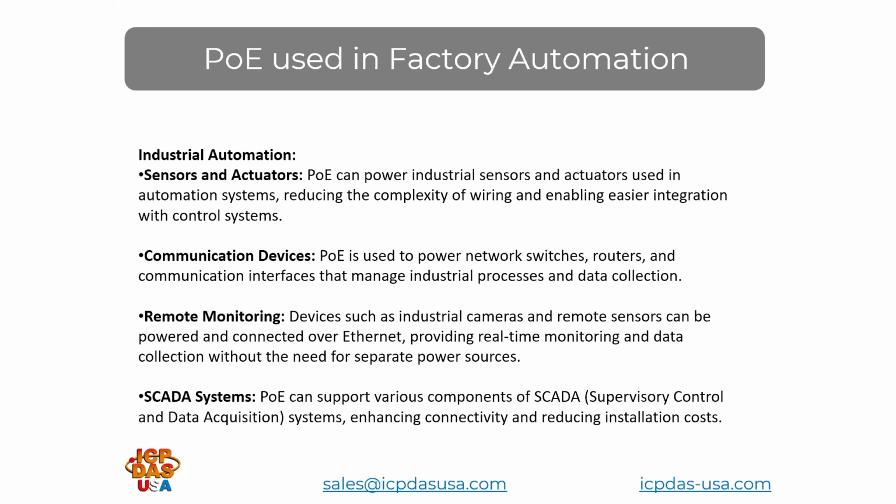PoE is also used in communication devices. We have a series of Modbus TCP gateways, which are PoE powered. They can connect to standard network switches, or if you use PoE power, you can power the device as well and reduce the need for separate power. You can use standard routers and communication interfaces that can also be used to share the data from these PoE devices to the cloud. For instance, like our MQTT switches as well.